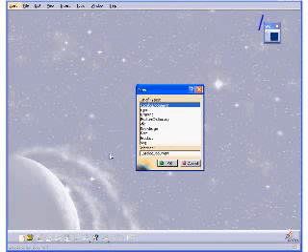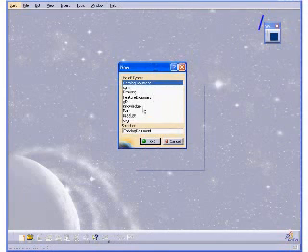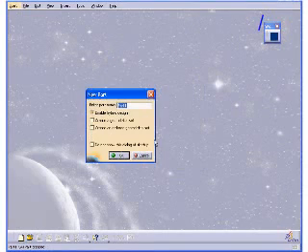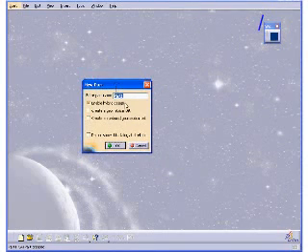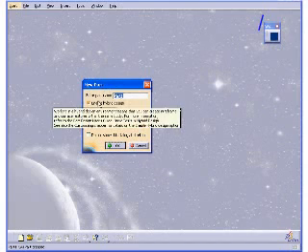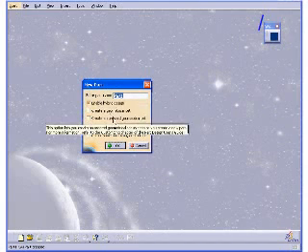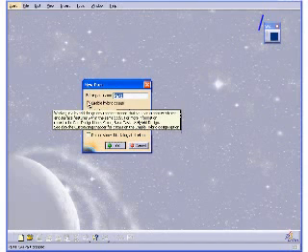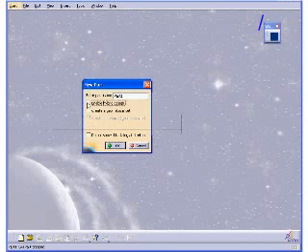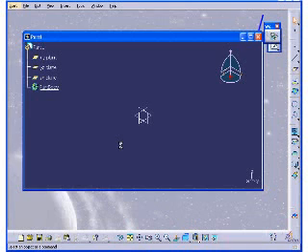Create a new document. I'm going to choose Part. Click OK. Catia prompts us with a new part dialog window, which we covered in the previous chapter. Enable Hybrid Design should be checked, and click OK.